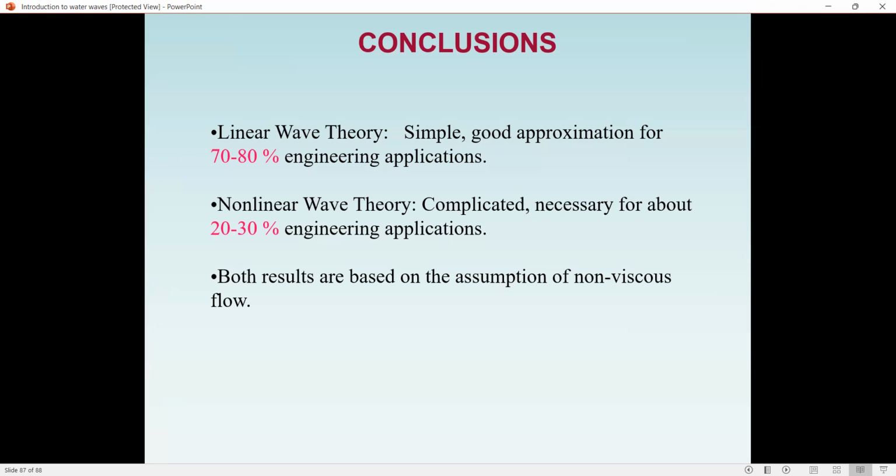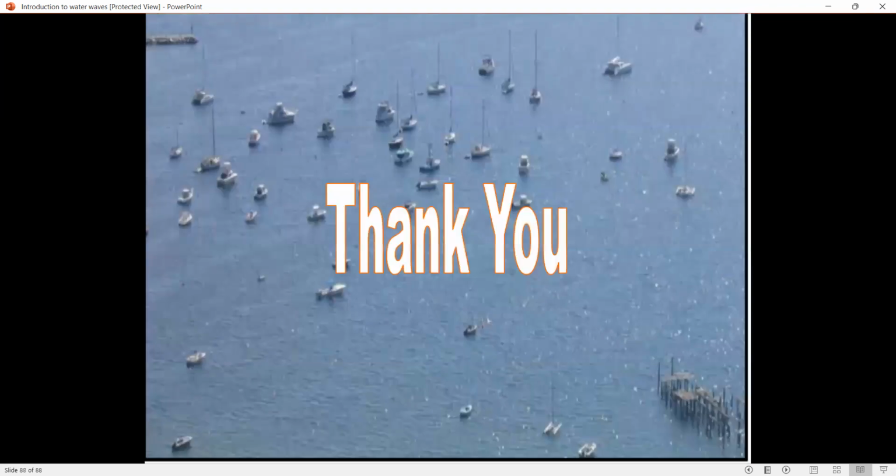To protect a shoreline, it is better to protect our beach, protect our mangroves, and protect even the corals. 30% to 50% wave retardation will happen if you have corals. We have large areas where corals exist, in the Andaman Islands, one of the best places for coral, and also in Kerala and Gujarat. Corals are there and they act as a natural barrier from wave impact.